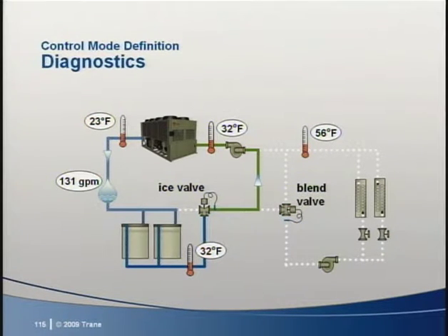If they are not the same, with a small allowance for pump heat, we know there is chilled water bypassing the tanks, and we should alarm the operator to that condition. We could do other similar system checks.